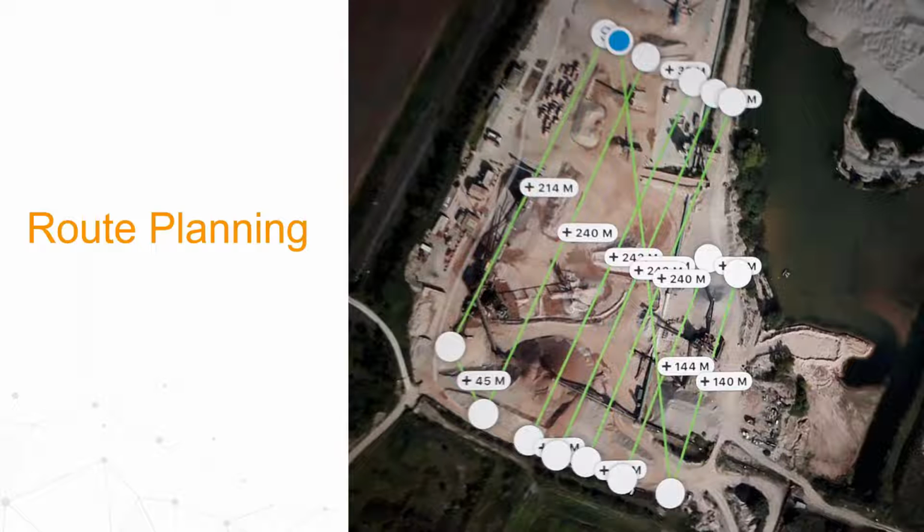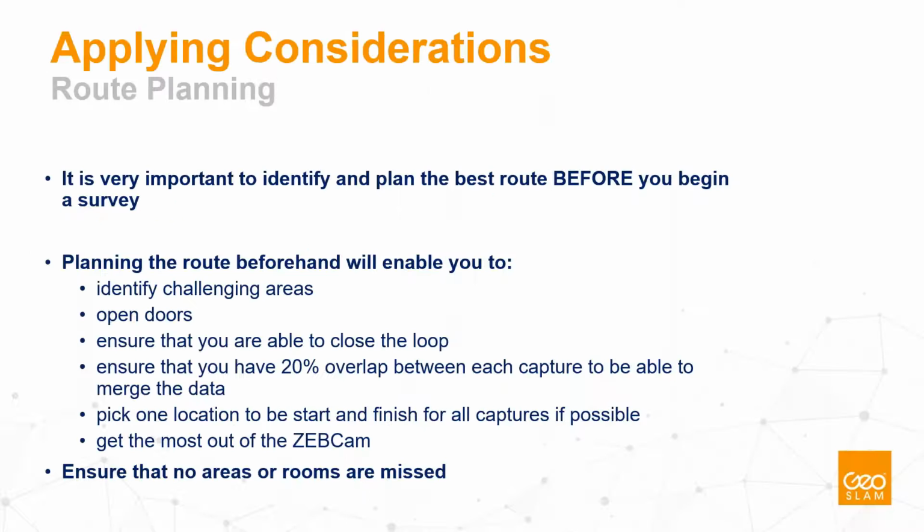Route planning is an important part if you haven't been on the site that you're going to capture, or it might be quite challenging. It's always worth thinking about where you're going to have your start and finish location, or how you're going to walk or fly with a system. If it is a capture inside the buildings and the project allows you to do so, if you open the doors, you'll be able to transition more smoothly through the environments and avoid any of those ghost points of the opening doors.